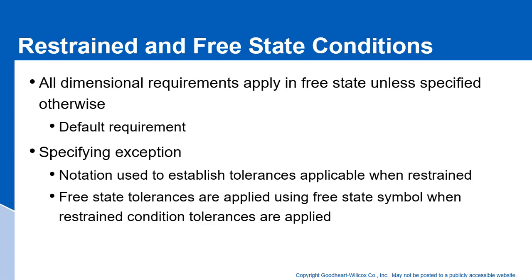Okay. So the point here is all dimensional requirements apply in the free state unless otherwise specified. And if you want your tolerances to apply at a restrained state, for instance, you have to put a note there.